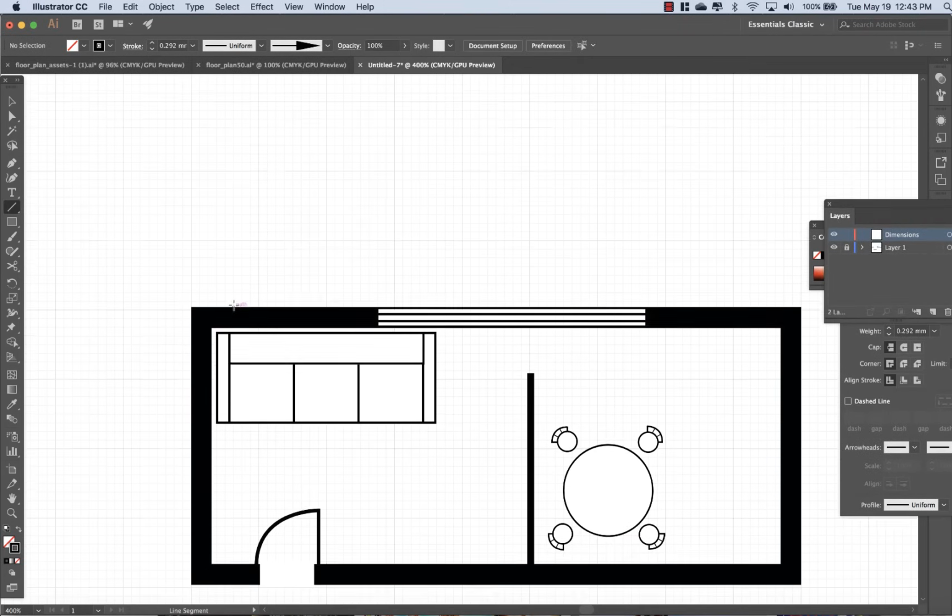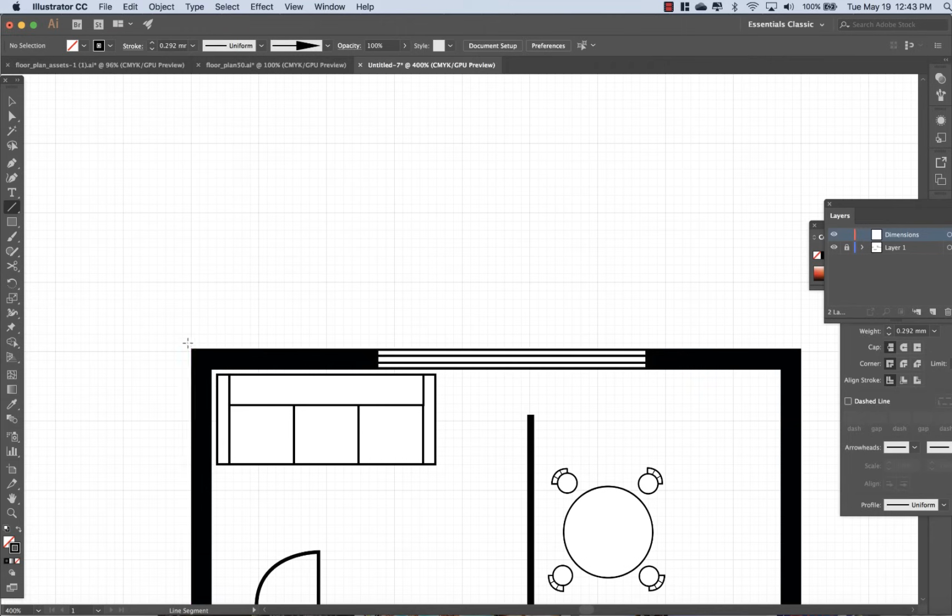And so what we're going to do is just start off with a projection line that extends beyond the actual building itself. And we can also use these purple sort of smart guides that pop up every now and again to help measure our building and construct our dimensions. So a projection line will extend beyond the building, but it doesn't touch the building itself. And what we're going to do is add 3 layers of dimensions similar to that of the example in the handbook. And for every line, we're going to give it 1 centimeter of space. So there's 1 centimeter, 2, 3, and then we're going to extend the projection line just a little bit further beyond that as well.